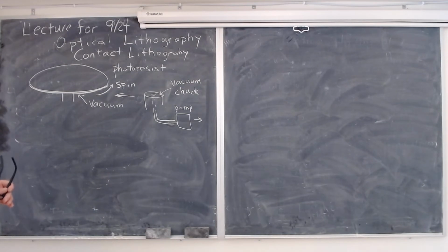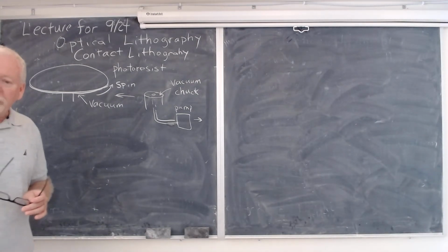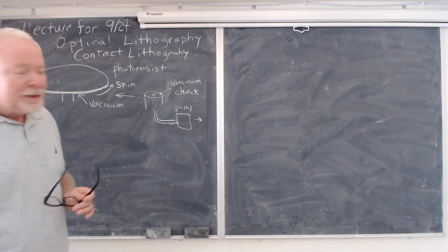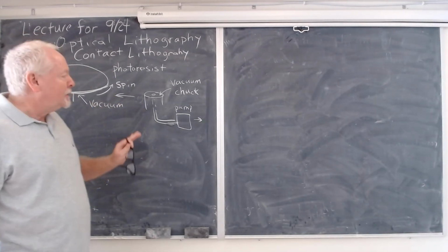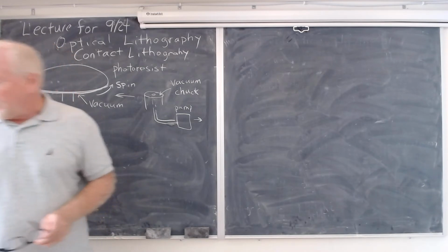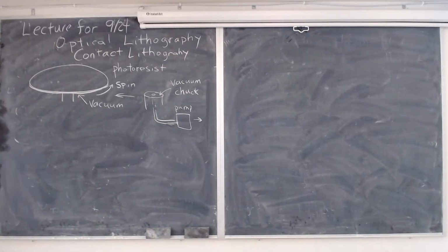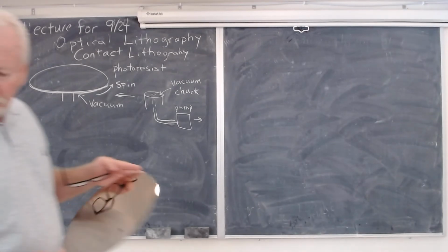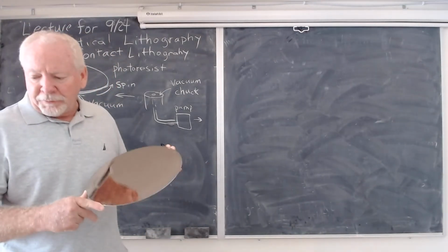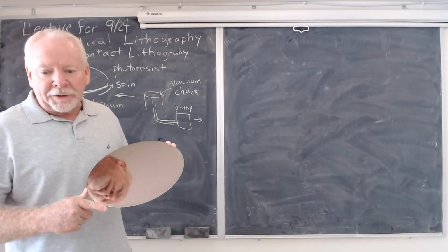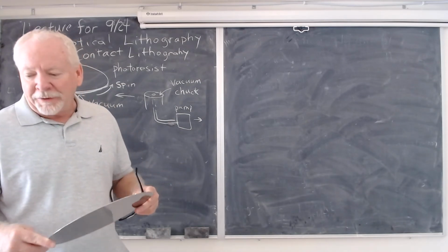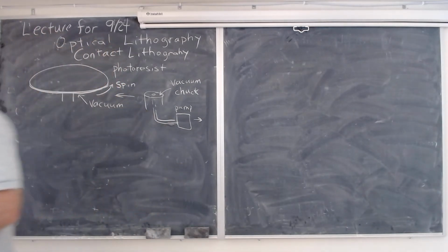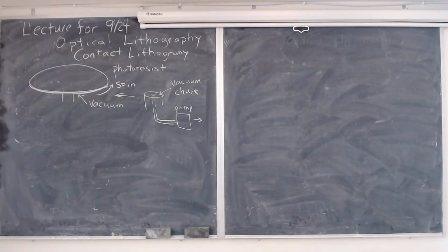And the main thing is you don't want the wafer coming off. So your choice of vacuum chuck can be important here, because if I was doing step number 23 on this, I wouldn't want this to go flying off the chuck and get destroyed after putting that much time and investment into it.